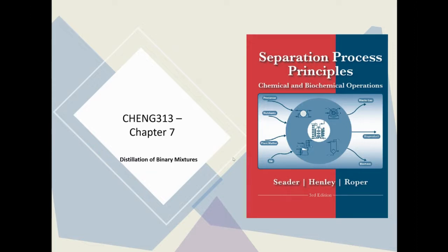Today we'll extend our approach, or our method, to include more than one stage, which is called distillation. Typical distillation, of course, but at least we'll give you some idea of how you can come up with the equations. And again, the equations are similar: material balance equations and equilibrium equations, and then the constraint. But now, instead of having only one stage, we will be having more than one stage, 3, 2, 4, depends.